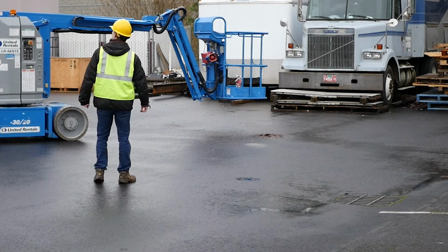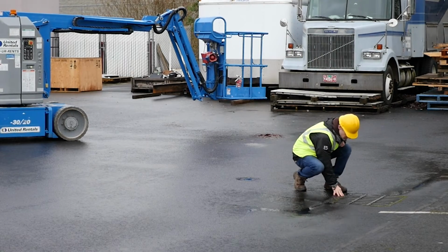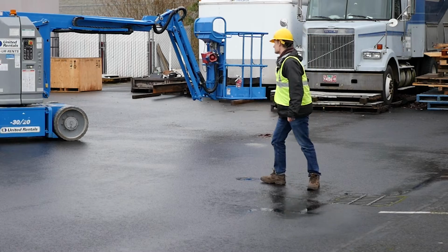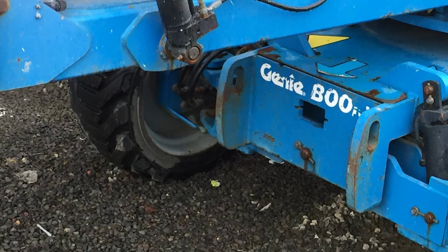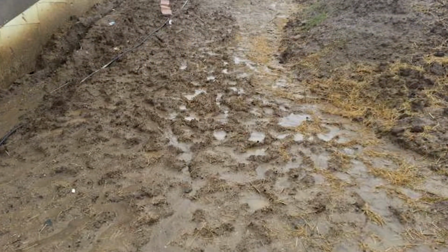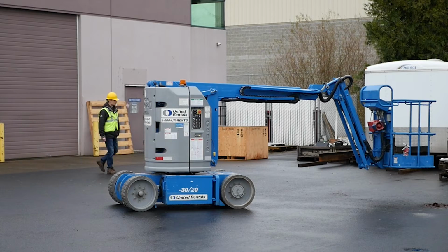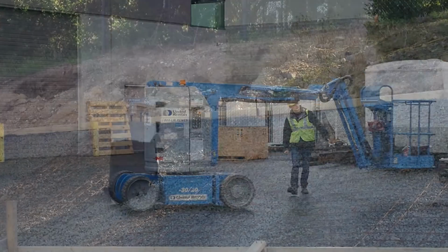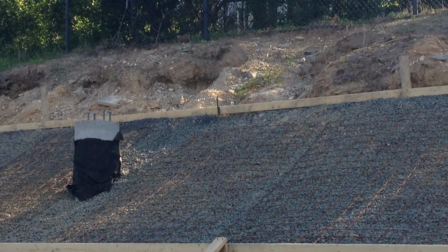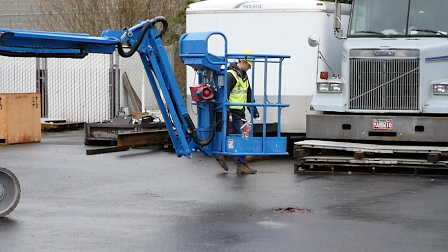It is important to inspect the work area before using an aerial device. Most accidents that occur are a result of a hazard that could have been identified if the area had been thoroughly inspected. Make sure the ground is strong enough to support the vehicle. Soft dirt or other surfaces may not be able to support the weight and may cause the vehicle to tip. Walk the work area and make sure there are no ditches, excavations, holes, or similar hazards. Check for excessive slopes or drop-offs that may cause the vehicle to become unstable. Check the area for loose debris, materials, or equipment.